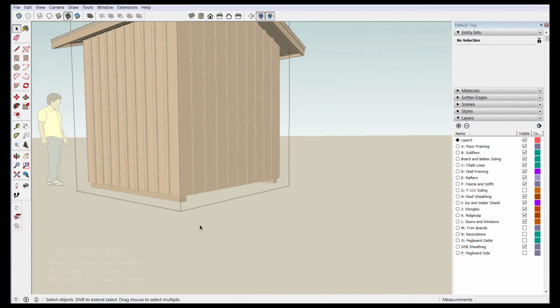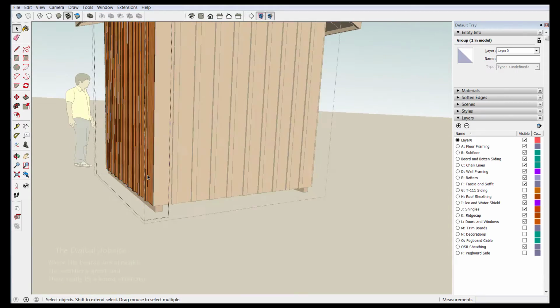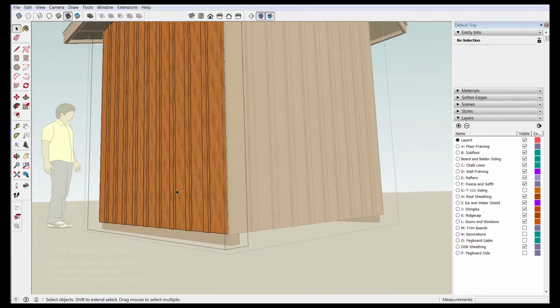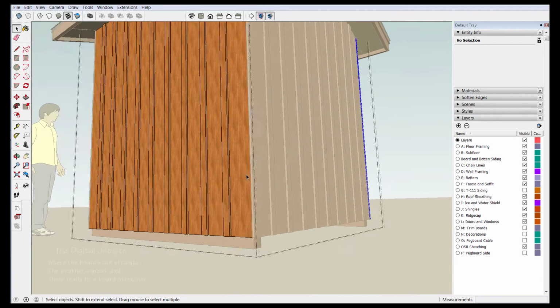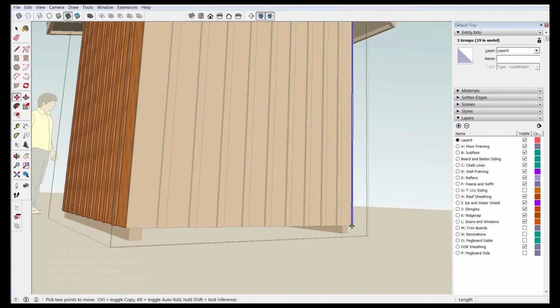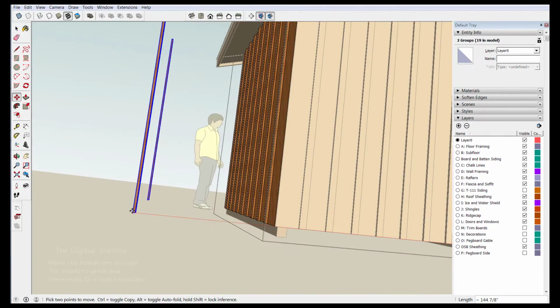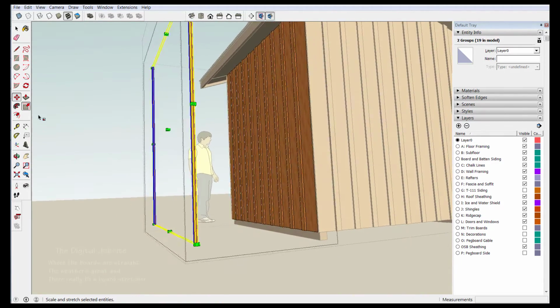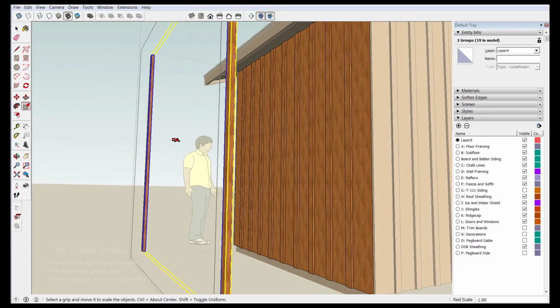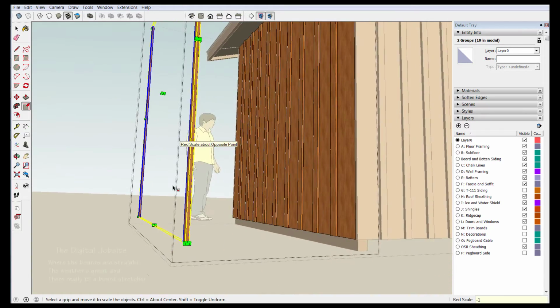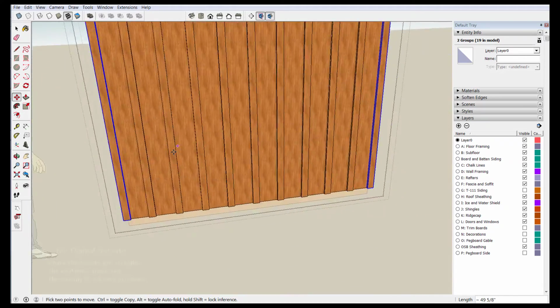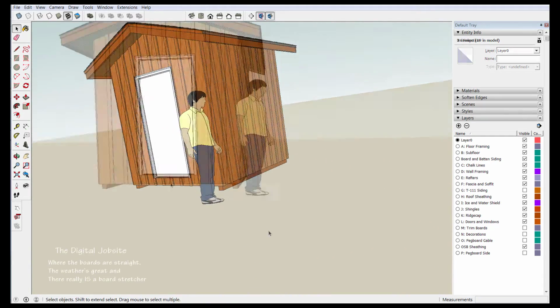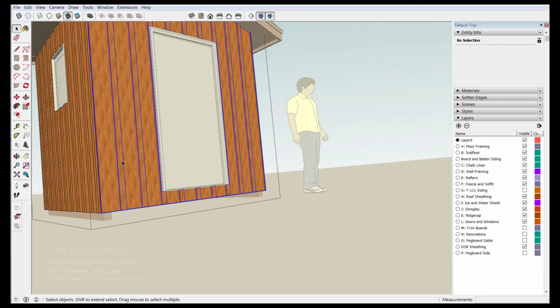And while we're in here, I'm just going to select these 2 battens and go Control C. And because I didn't set this up as components in the first place, the changes I made on one side aren't applying to the other side. But the steps are pretty few to make the change, so I just paste in place the battens from the other side. Just going to move them over in this direction, take the scale tool and reverse them to get the angle cuts right on the top. -1, enter, and then move these into place.